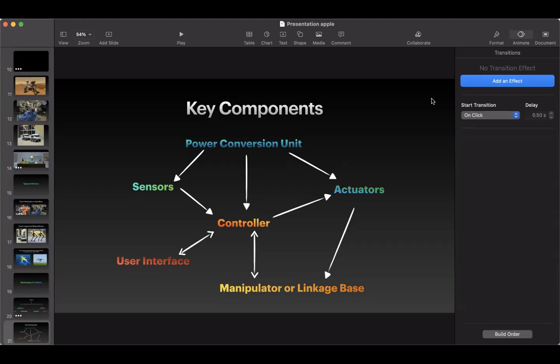Thank you, sir. Right, no worries. So that is a very good question. Like Himal said, if we give power from a 12 volt battery to a 6 volt motor, the motor may get damaged. Because the motor is 6 volt, it is recommended to work with 6 volts. If we give a large voltage like 12 volts, a 6 volt motor can burn out. But when it's practical, a 12 volt battery can often run a 9 or 10 volt motor without a big problem.